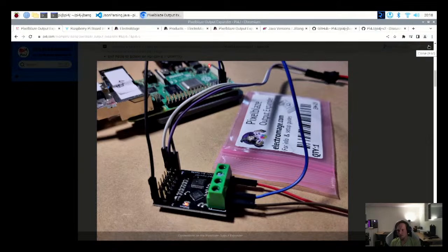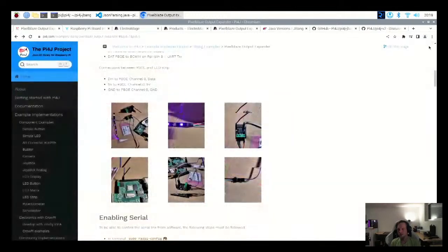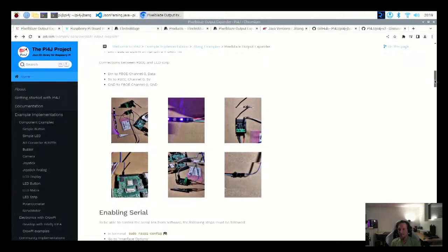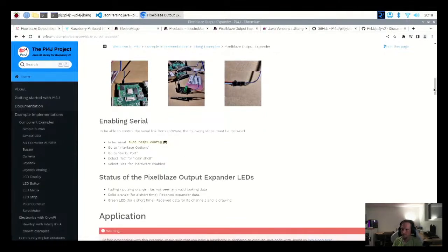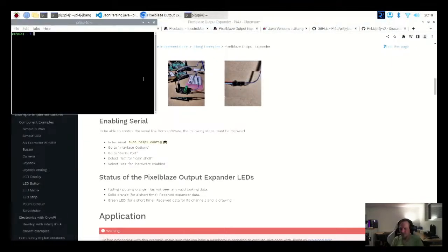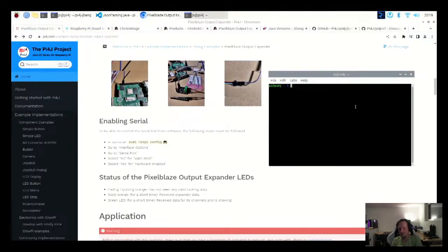In the end, what we're doing here is building a circuit, even if we're not just powering an LED or a light bulb. Circuits, as the name implies, are always a circle, so something has to come back. And if you don't do this, you end up with timing issues, and the LED strip will do something, but not the thing that you were expecting. I think what this means is that you have a floating signal, so you don't even know if it's properly reaching 0 or 5 volts, and thus it doesn't properly create the signal that the LED expects.